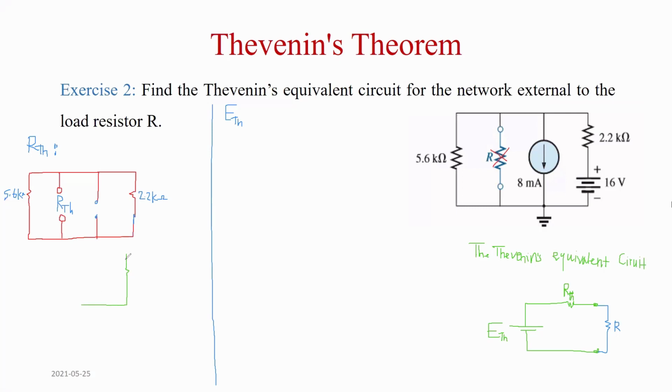Now the open circuit branch is not gonna affect my analysis. There's nothing here, no current going through. So this branch, remove it completely. So 2.2 kilo ohm, this resistance between these 2 points is exactly like these 2 points. There's no difference. So I can connect it here.